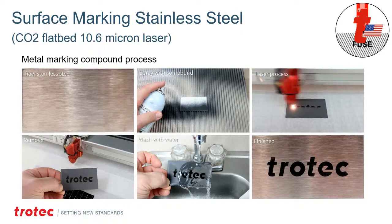It typically comes in spray cans. It comes in a paste that you can brush on. You can also buy it in a tape where you can basically take a piece of tape and place it on the surface of the metal. Then you stick it into the laser, and laser the material using preset settings for the metal marking compounds. Take it out of the laser system and then just place it under your sink with water, and the excess material washes right off.